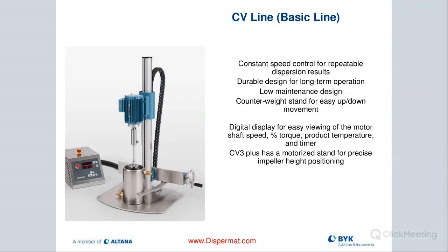With this system, it's also capable of measuring temperature. You have a timer function. It also gives you a torque value, the percentage of torque. That's kind of an indirect measurement of the viscosity of the mill base. So that's a really nice machine.